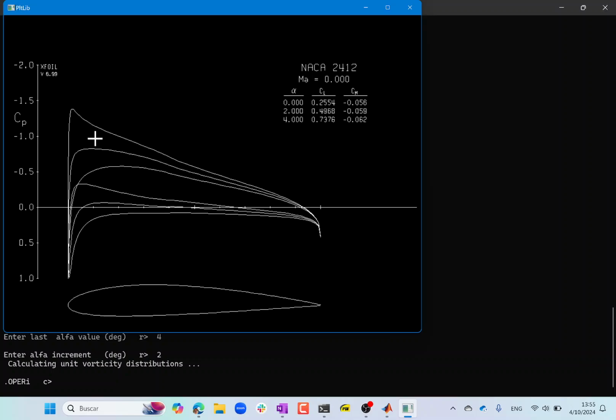Okay. And now because the flow goes like this, and the flow has to go around, the fastest flow actually lies almost exactly at the same location as the stagnation point, but on the other side. That's what this is. This is zero velocity. This is the fastest flow, which is almost at the same location, but on the other side. So, yeah. Negative 3.81. So basically from here to here it's going to be slow velocity, but on the opposite side of the zero point, it's going to be the fastest.